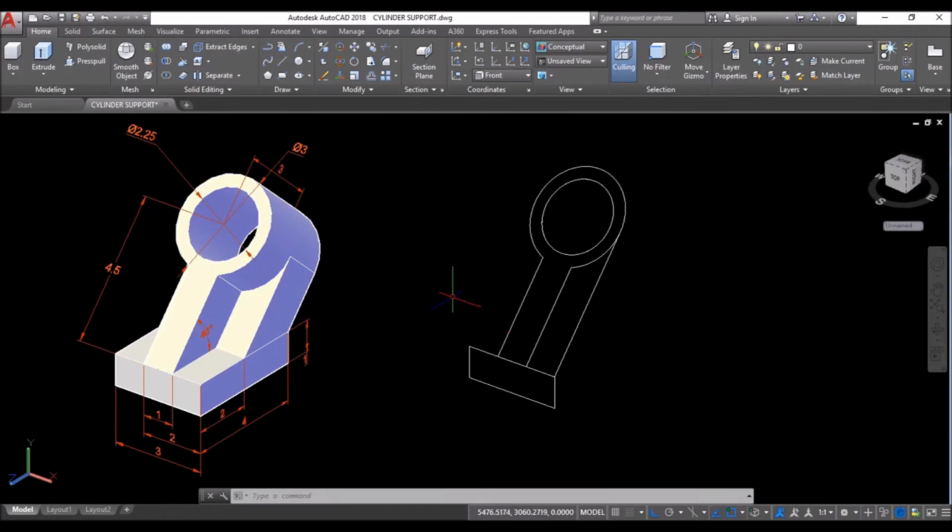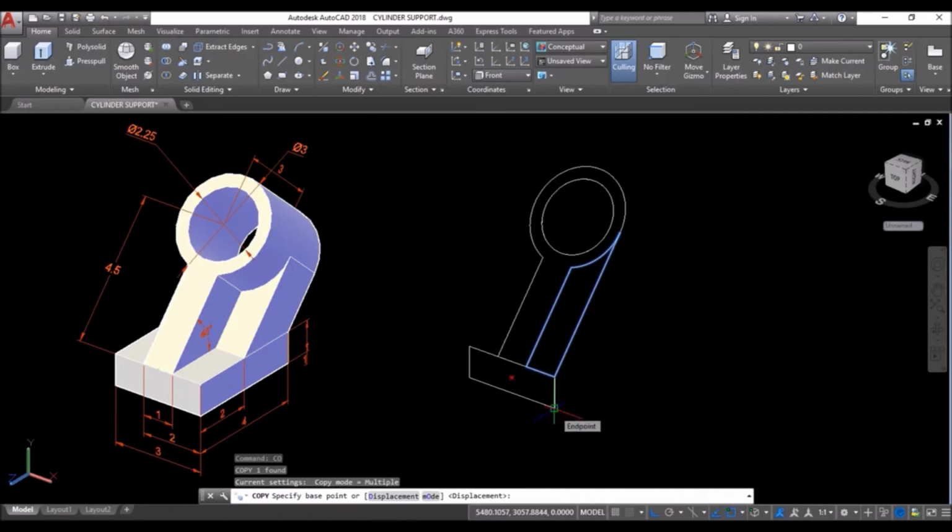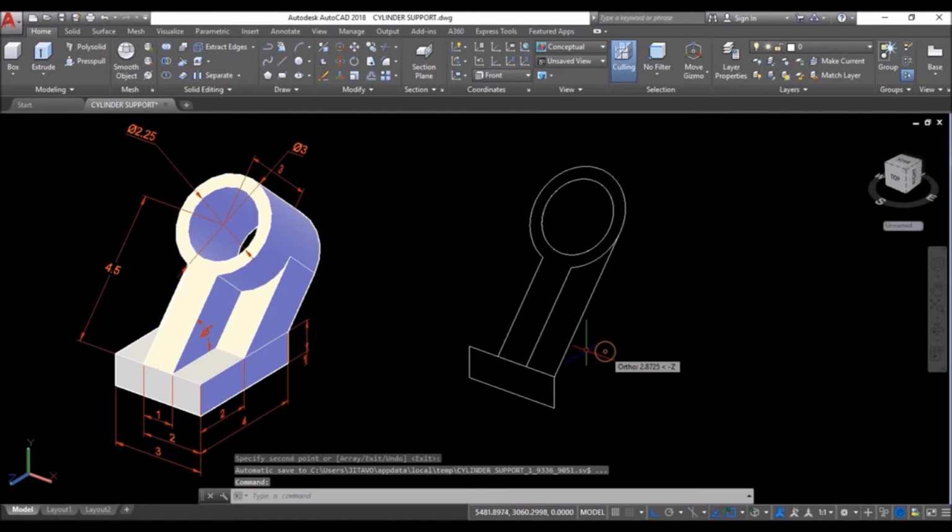Then I'll need this polyline in two numbers. The reason being, one will be extruded till the endpoint along the inclined plane and another one will be extruded along Z axis by 2 units. Then I'll subtract the front part from the back part to create this part. I'll show how to do it. First I'll make a copy of it. So select it, type CO and press enter. Then click at any of the snaps twice and then press enter to create a copy.